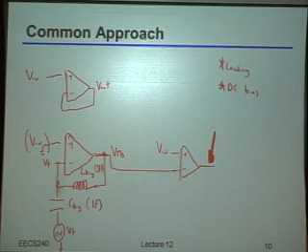Oh, so the question was, do you have to add any loading here? The answer is no, because I am driving that with a voltage source now. So I just have to make sure that I'm mimicking the loading on the output of the op amp. And by the way, that's again why usually you really want to break the loop at these high impedance nodes. Because if you break it at a high impedance node, you know that driving it with a voltage source doesn't matter because it didn't change anything. And you know that the feedback was driving an infinite impedance, so that also didn't change anything.